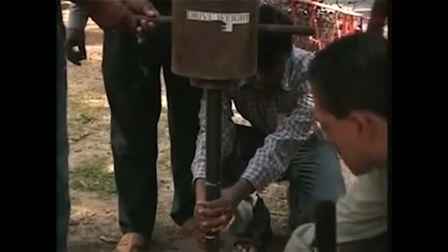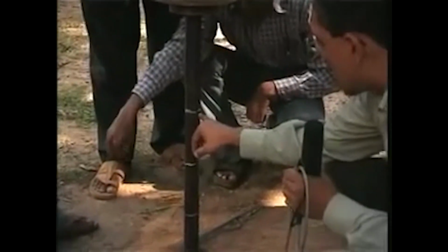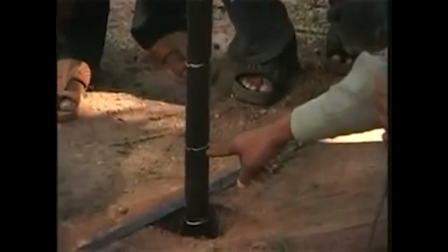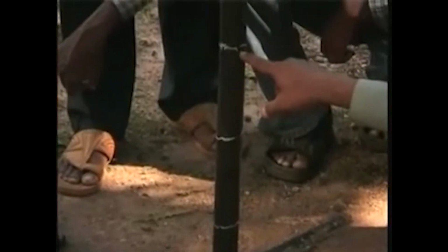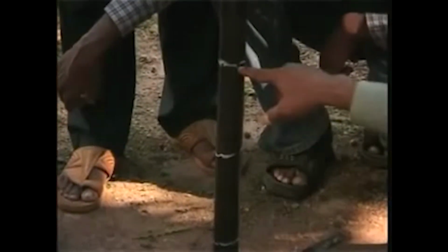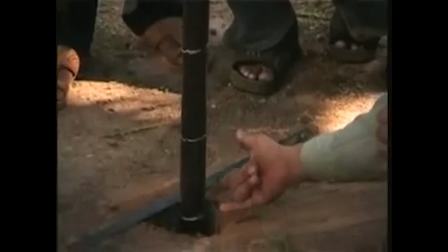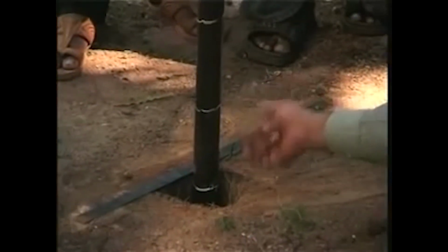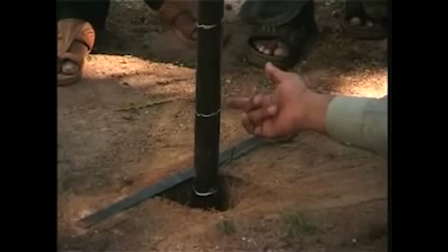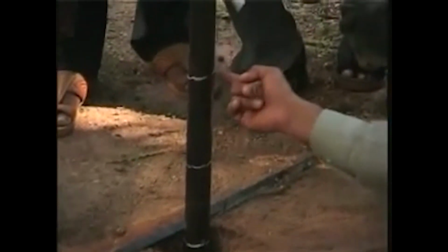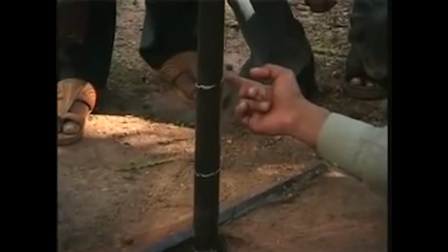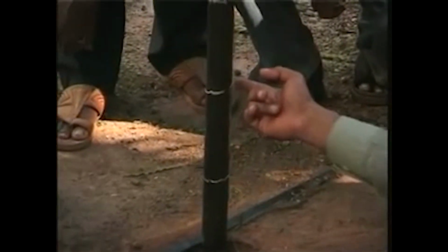And what you also see is that we have three markings at 150 millimeter spacing: one at the top of the hole, then one 150 millimeter above, the next one 300 millimeter above, and the third one 450 millimeter above the top of the hole. So what we are going to measure is the number of blows required for the penetration of this length from here to here, then the number of blows required for penetration from here to here, and finally the number of blows required for penetration from here to here.